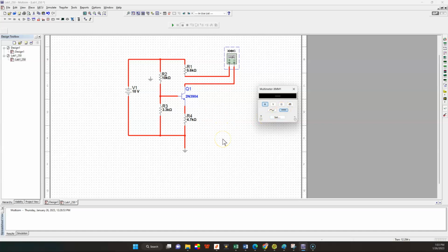All right. Then the other thing, adjust it on measuring the amp, DC, because many mistakes happen in the lab. Usually the student forgets to connect the digital multimeter to the amp terminal because you have different terminals. There is the one to the right, I remember, for the voltage, and the one in the middle for common, that's the ground. The one to the left is the amp. So you got to make sure about that and adjust the scale of the meter, and then turn on your circuit to measure the collector current.